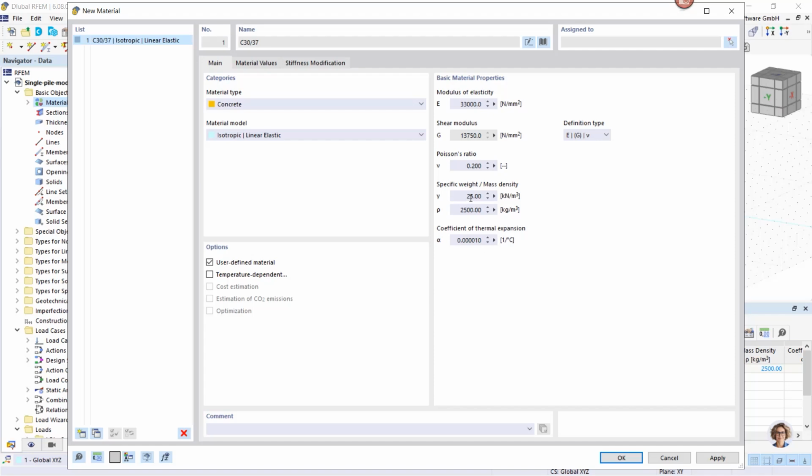The specific weight is reduced in this example as it is a 1D object, and in the area where the cross section of that pile would actually be placed, there is a soil material placed. And this soil material already has weight, so as they overlap the cross-section of the pile and the soil self-weight, we put here a smaller weight so that the sum is the right value.